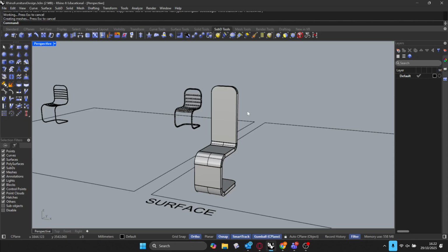Nothing has a perfectly sharp edge. So if you want to start to get realism in your models, realism in your CGIs, put just a slight fillet on edges. A lot of the rendering softwares like D5, for example, allow you to put an imaginary fillet on after the fact. So even if you've modeled it with a sharp edge, you can put it on in D5 when you put the material on. You can just put a slight radius on the edge, but you can also model it in there as well.